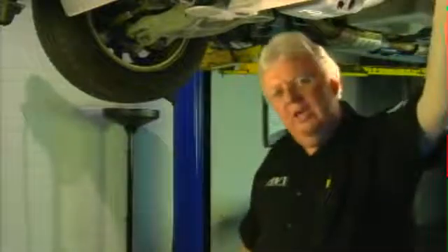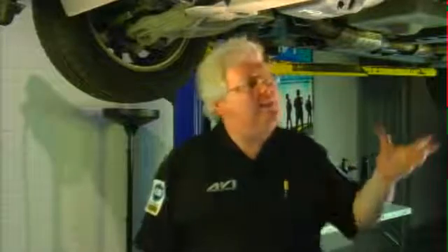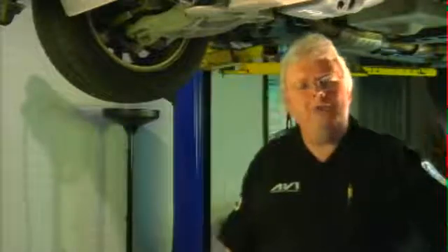Then do a good visual inspection, including grabbing things and pulling up and down, using a spring scale if you've got one, to see if you have anything that's loose in the way of the steering. And we also discussed a little bit about what's coming up in the next segment, Chapter 2, on suspension systems, a little bit about front suspensions. Rear suspensions the same way. Inspect, inspect, inspect. Bushings, mounts, the components themselves, any kind of stress in the metal and so forth.